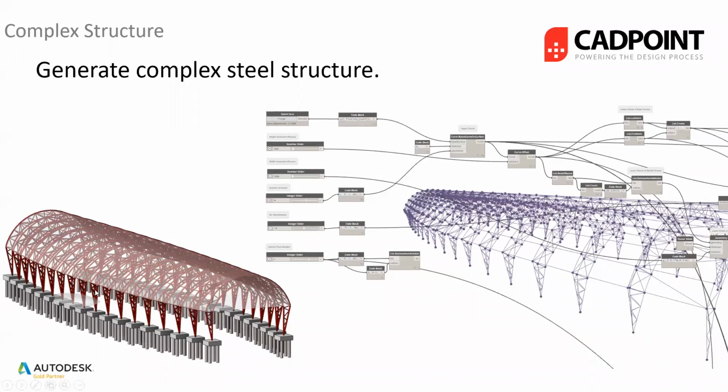Obviously, your foundations are at different widths. You want your structure to be some sort of consistent implementation. So when you hit the script, it will find the center point of each of these foundation pads, and it will run this lattice structure all the way up, and it will change the width of it and maintain the height of it that obviously you want to maintain, and then you can create a surface over that as well. So looking from an engineering point of view.